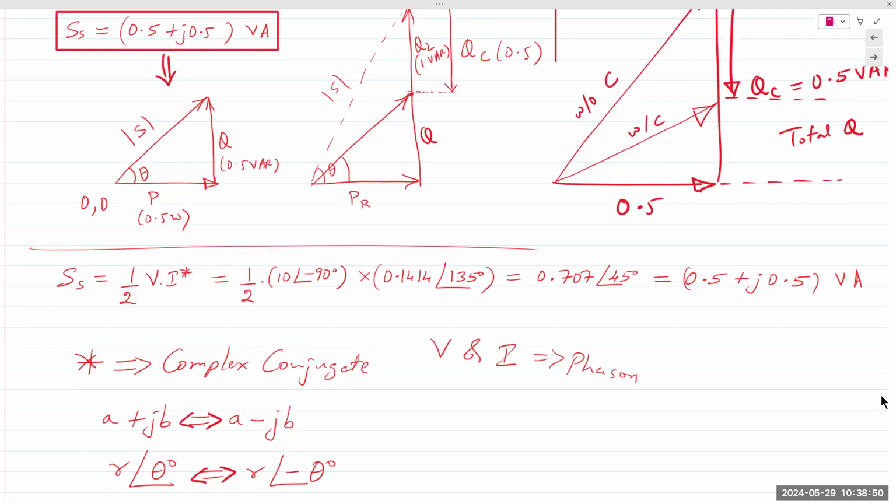So now it's a 10-watt charger. The USB spec doesn't change. It still stays at 5 volts. They increased the tolerance a little bit, like 5.1, 5.2 volts. You can't increase much beyond that because that's the actual spec. That's what all ICs and chips handle. 5 volts. But you keep increasing the current requirement. The higher the value of the current, the faster it charges.